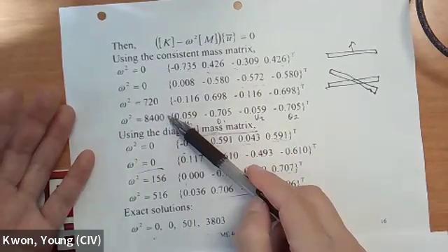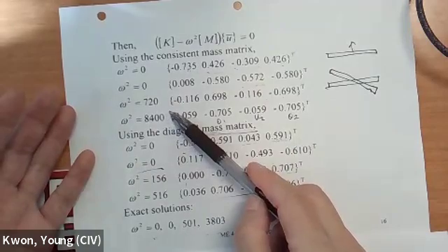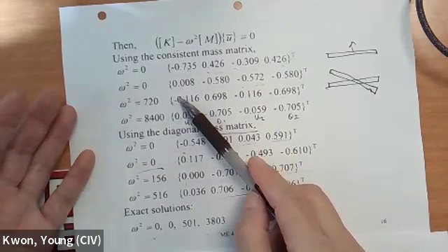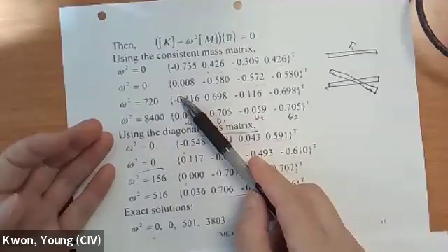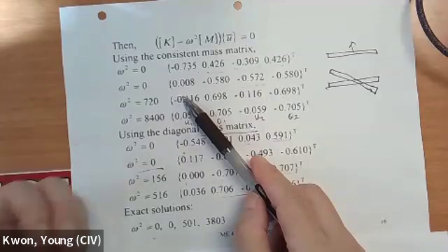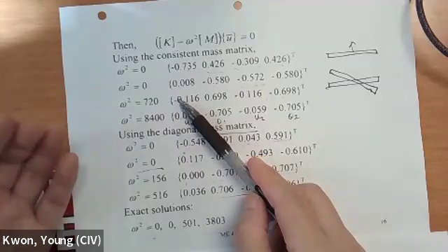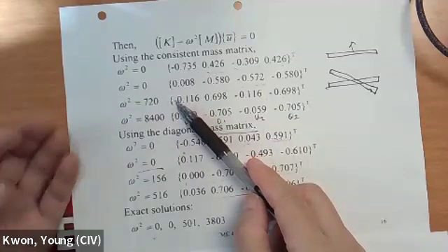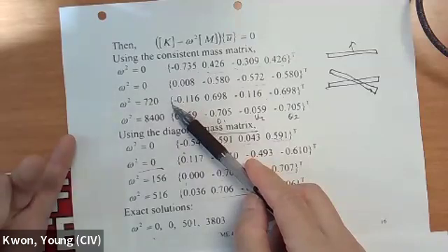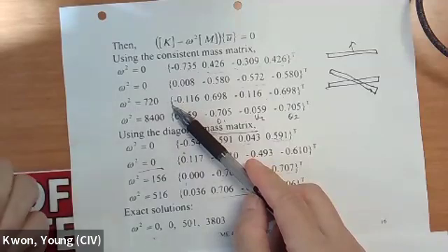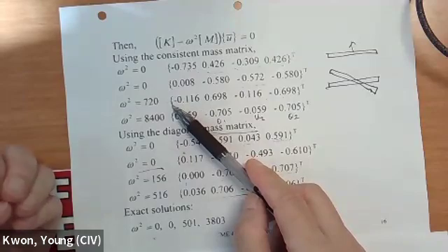So mostly you are not going to find all 1,000 eigenvalues, because we don't need all that information. Most of the time we are looking for the lowest eigenvalues, the lowest natural frequencies. We start maybe from 1 to 3, up to 10, depending on how many you need.